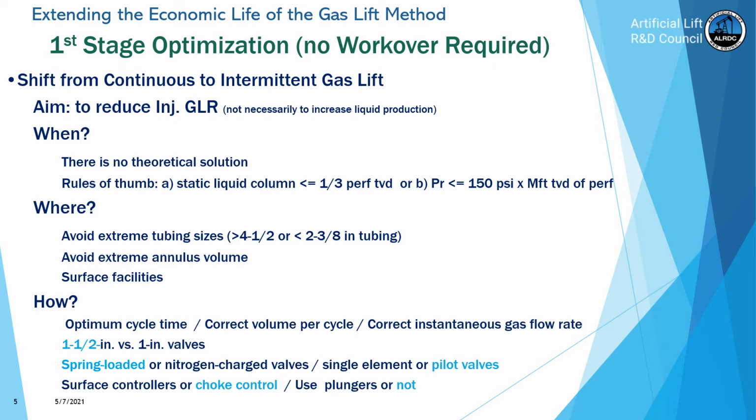Well, of course, with an orifice valve, when the intermitter closes, all the volume in the annulus will go through the orifice, and then you're going to have to increase the pressure again inside the annulus by a lot. So no. The best combination that you can have, and probably the only one in many cases, is an intermitter and a pilot valve.